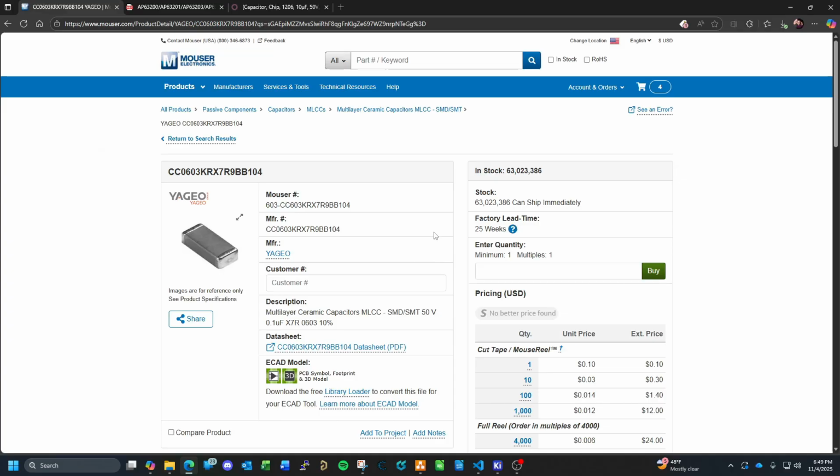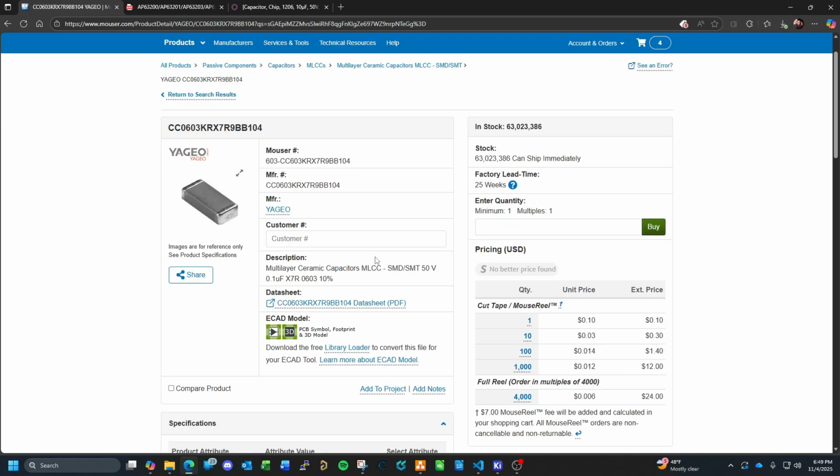Go back to here. And again, this part you're going to use like water. Designs everywhere. It's primarily used to help filter out noise, help set up timing circuits. It's used on the PIC and the ESP32 on their enable and master clear pins, respectively, to basically delay their power up, their initialization, until the main power supply rails are stable. It just kind of gives them a slight delay through an RC network. Okay.